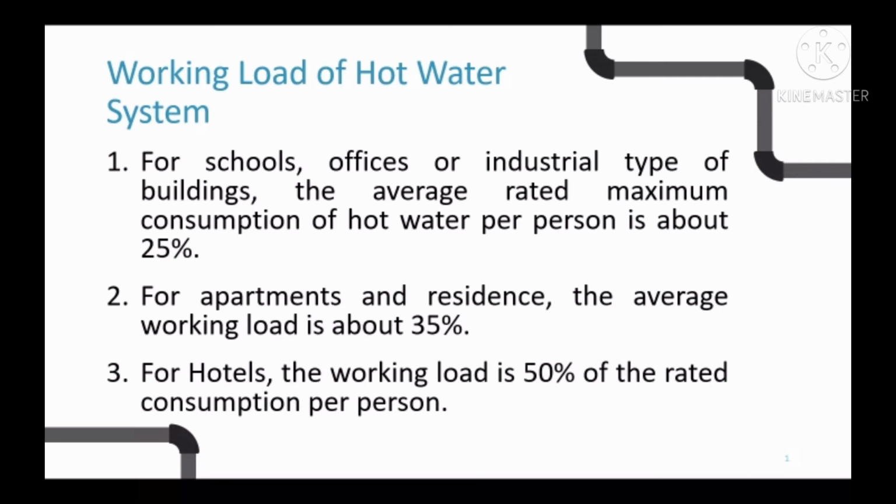Running the faucet for 1, 2, or 3 minutes while waiting for hot water to arrive at the faucet or shower is one cause of this waste. The solution to this problem is a hot water recirculation system. It prevents this waste by passing the lukewarm water in the hot supply pipe into the cold water line back to the water heater instead of dumping it down the drain.